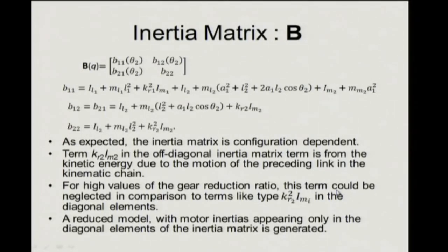So, you can then build up the full inertia matrix, and so you can calculate term by term exactly the method which is given there. You just expand it out and you will get expressions like this, slightly longish expressions. Okay. On second thoughts, I will just upload this also, so that you can compare them. So, you will get composite terms like this, which involve moment of inertia of link 1, the transmission ratios and things like this.